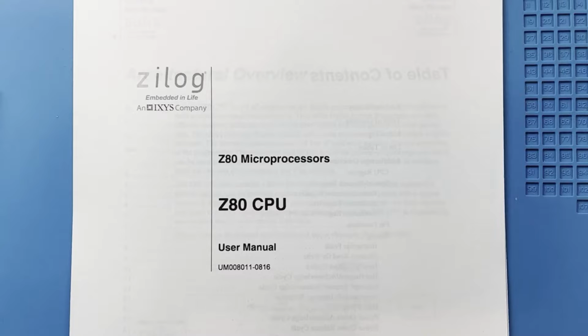It has 8 data pins and 16 address pins, so it can address 64K of memory, 0 through 65535. It supports input and output through the use of an 8-bit I/O addressing system, meaning it could support 256 input or output channels. It was actually designed for embedded systems like cash registers and industrial robots, but it became one of the most widely used CPUs in computers in the late 70s, early 80s.